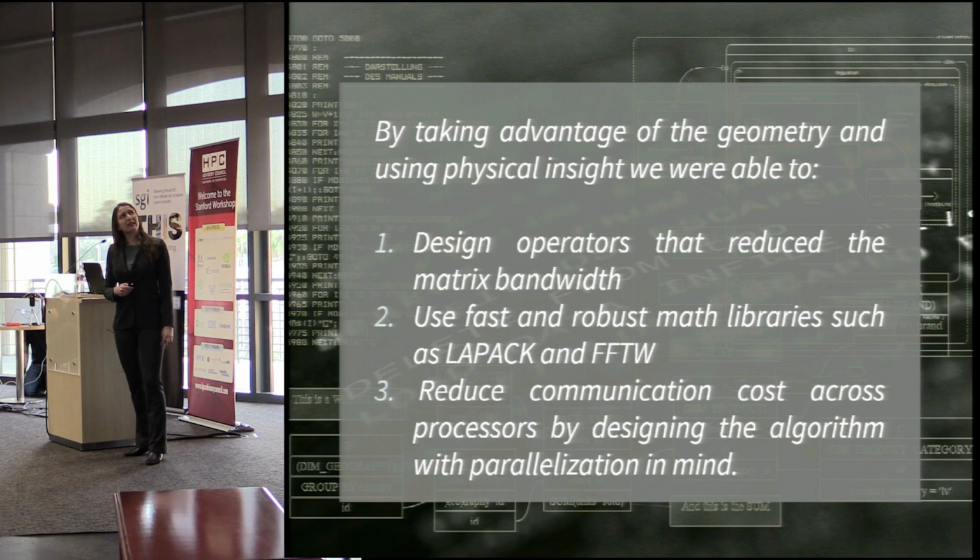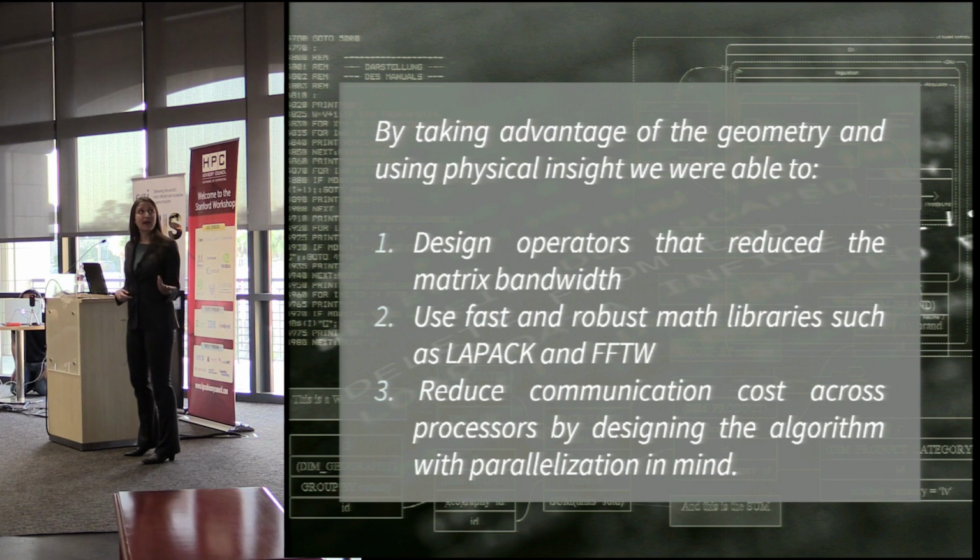So by taking advantage of this geometry, which is simple compared to, say, flow around an aircraft, and using physical insight, we were able to reduce the matrix bandwidth, which enabled us to use fast and robust math libraries like FFTW and LAPACK, which are also portable.